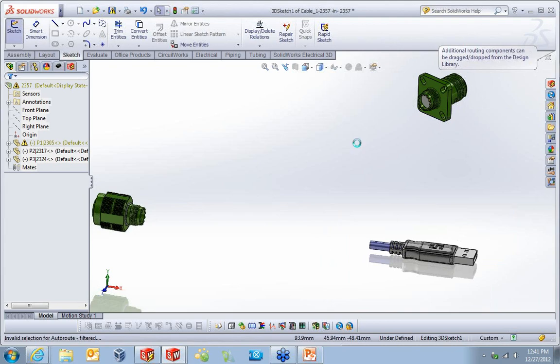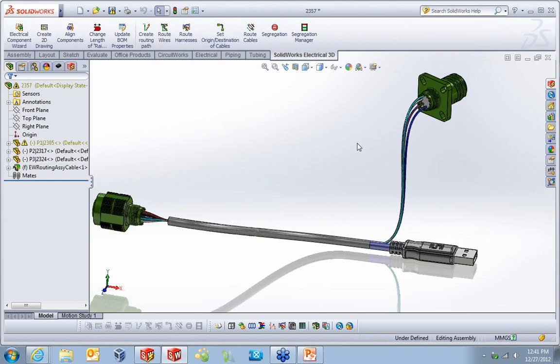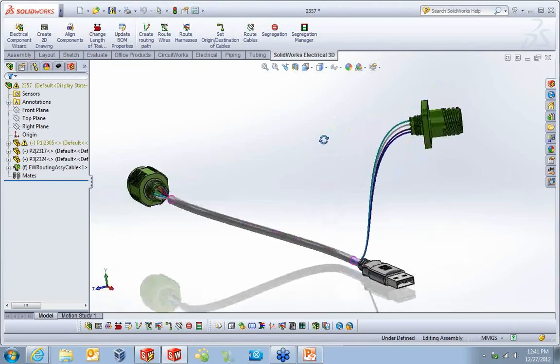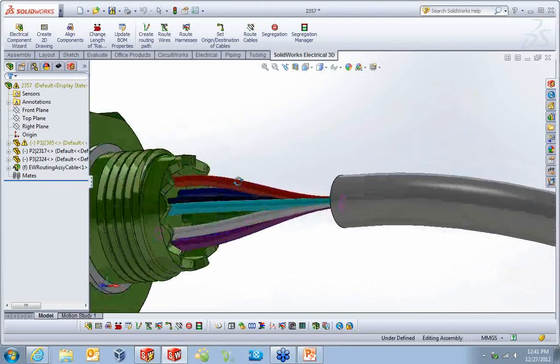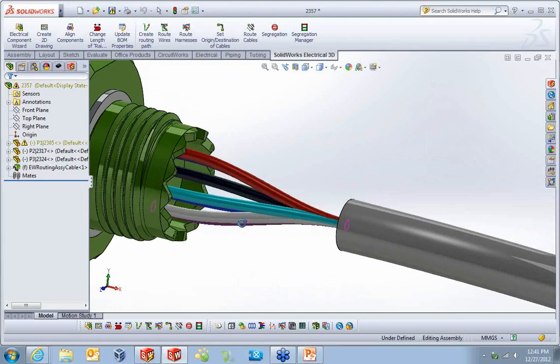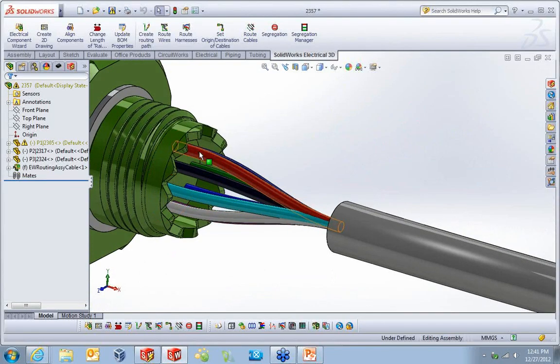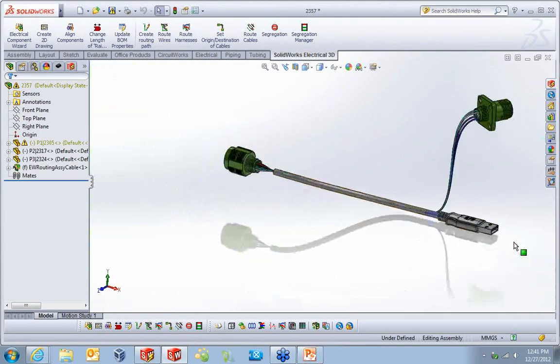Not even a real schematic, a pictorial diagram of the schematic, which anybody can do. And there it is. Got the color of the wire already baked right in there because that was called out on the schematic. It's got the pin locations on each one of the parts.